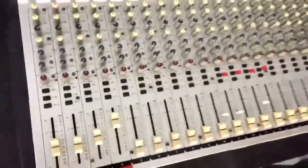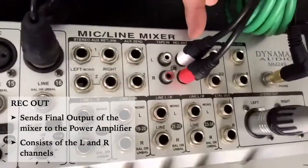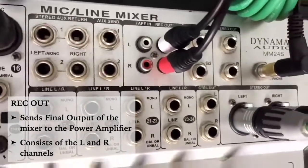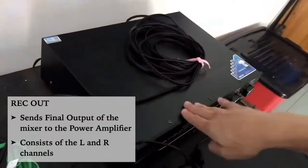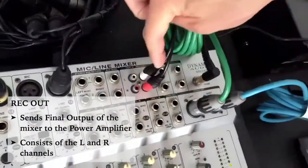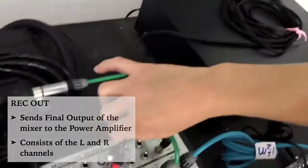Okay, so the next thing that I want to talk to you about is this part of the mixer. So let's come here. This is REC out. It stands for recording out. Currently in our church, I use this one to send audio signal out from the mixer to our power amplifier here. This is the power amplifier, so I use these red and white RCA cables to send the audio signal out from here all the way to the back of this amplifier, to be sent to the speakers. So this is the main output.